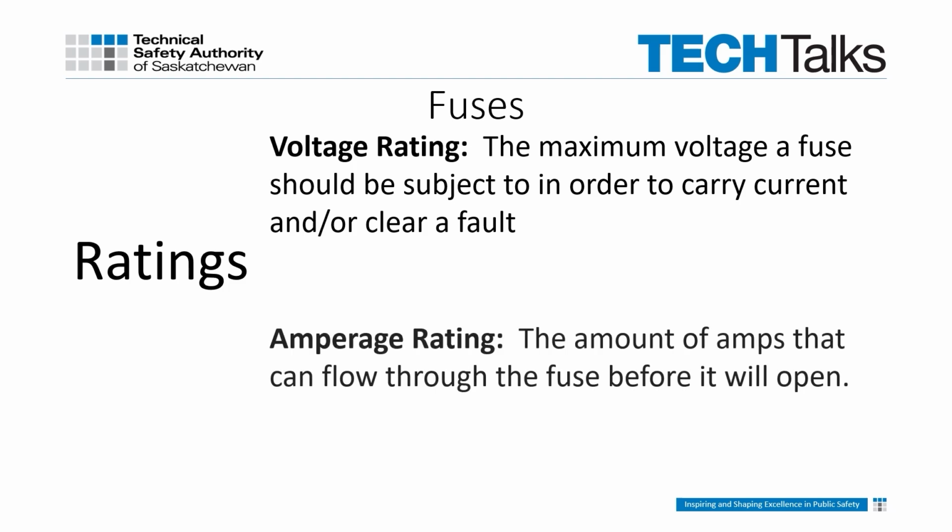Amperage rating is the amount of amps that can flow through the fuse before it will open. Fuse sizes in amps should be adequate for the type of installation. The size of the service, feeder, branch circuit conductors, and the loads supplied will determine the proper size of fuse selection.